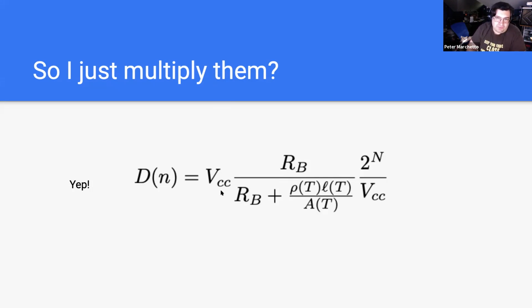So let's go back for a moment here to a much simpler system. With an Arduino, for example, I have 1,024 possible values on its analog to digital converter. That's 2 to the 10th. Usually it's referenced to either 5 volts or 3.3. 5 makes the math relatively easy. So you get about, I think it's 4.8 millivolts for every single one of those least significant bits.